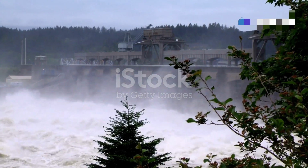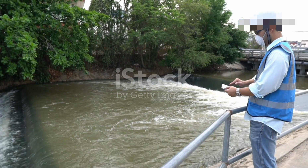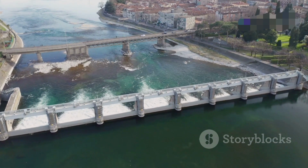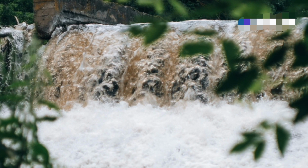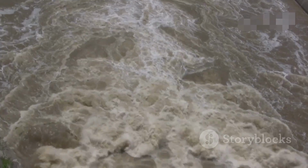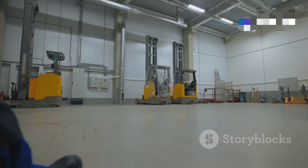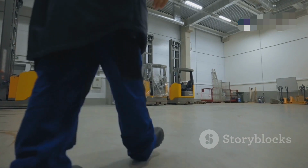Section 8. Breach scenarios and their impact on flood waves. When performing a dam break analysis, it is often necessary to consider multiple breach scenarios. This is because a dam might fail in different ways, or under different conditions. For example, an earthen dam could fail due to piping, which is internal erosion, or due to overtopping during a large flood event. These different failure modes can lead to different breach characteristics and, consequently, different flood waves. By analyzing various plausible scenarios, engineers can get a more complete understanding of the potential risks.